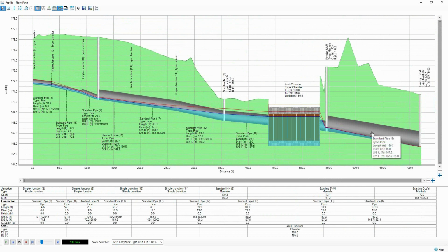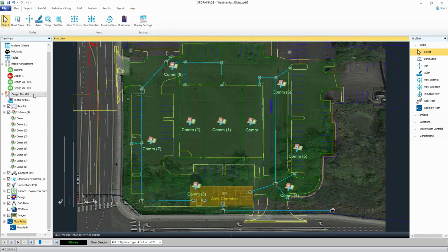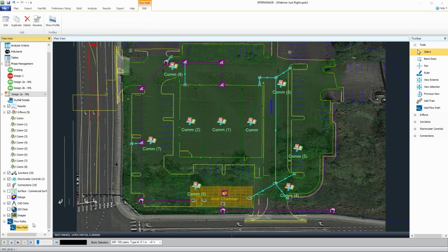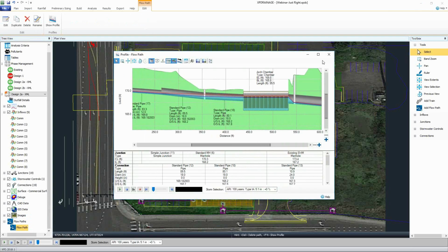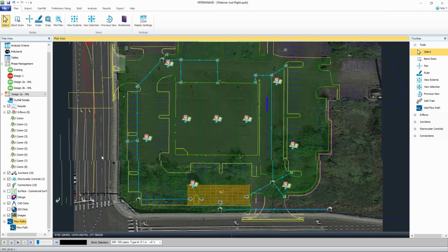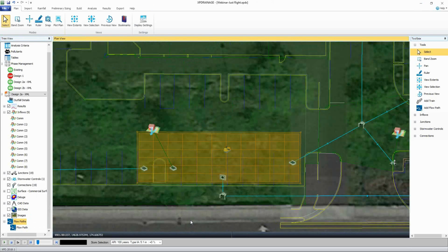So this is probably going to give us a more cost-effective design as opposed to that other option where we just started with the rational method. Okay, that'd be a little oversized, but you get the idea. So that's really the different combination of the pipe sizing approaches. As I mentioned before, there's kind of 6 different pieces that you can absolutely move through all together, or just do preliminary sizing, or just do the full dynamic hydraulics.